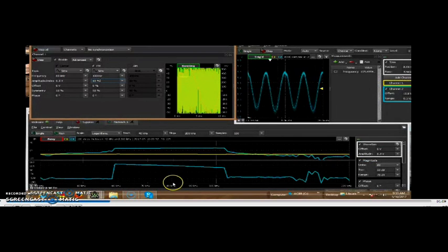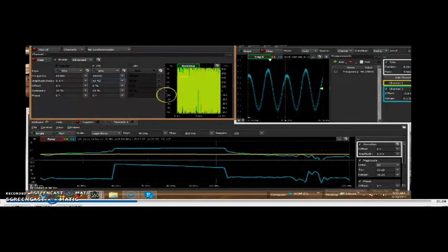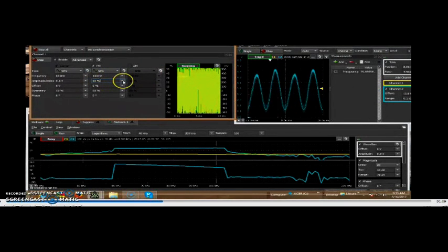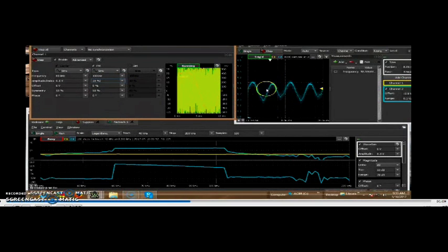This is a demodulation of an FM signal. FM signal, carrier frequency, 50% modulation index. We are getting the demodulated waveform. As long as the frequency swing lies within the lock range, we are getting the proper demodulation. You can see now we are still getting the demodulation.